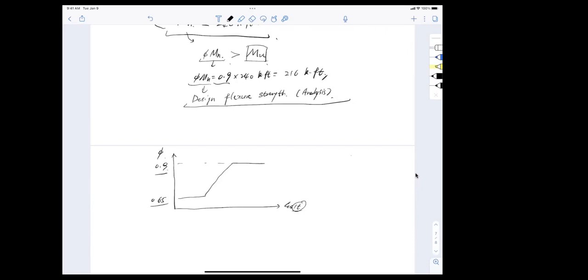So this comes again from the strain diagram. If the epsilon cu on the compressive side of the concrete is 0.003 at failure, and then my strain here is epsilon s, right? This is perfectly fine if I have a section with one layer of reinforcement. Of course, the strain in that layer is the same for all of them.